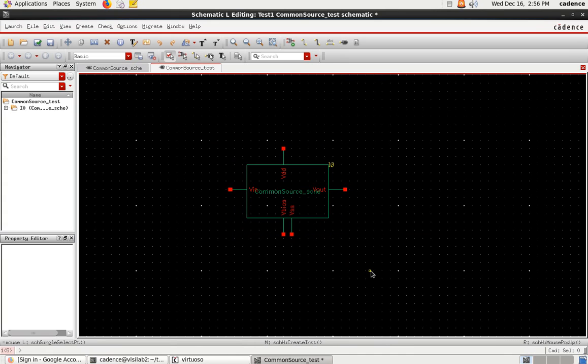That means I have to connect all the analog components, then check or verify the results. So how do we do that? First we'll add VDD, V bias as well as VSS, because all are DC voltages. So I'll give VDD, VSS as well as V bias first, then I'll give V in, then V out.